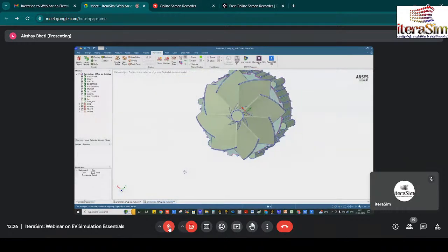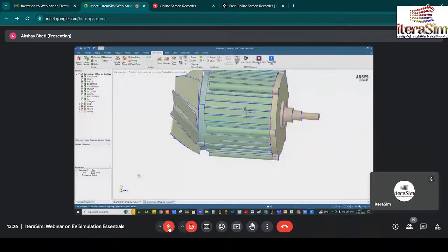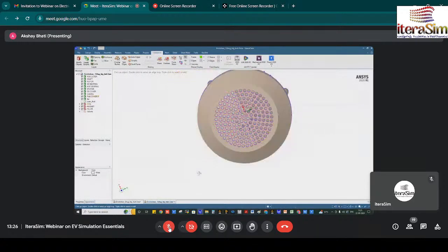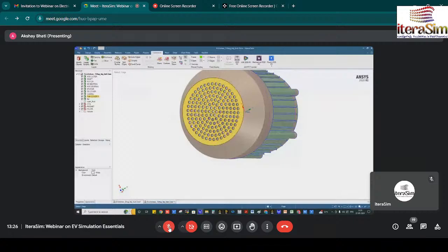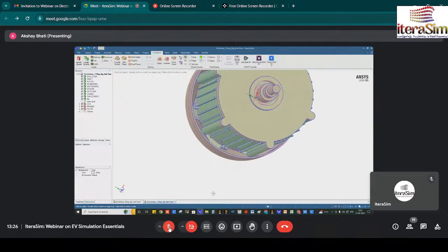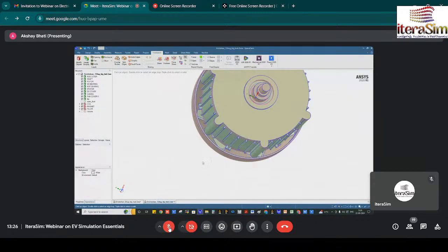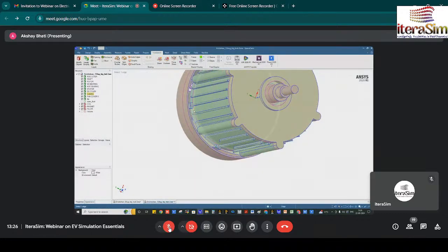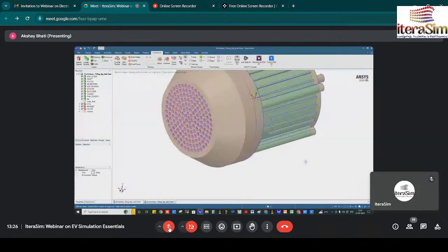You can check that fan over there to flow the air. After that, the fan cover will come, then you will get an idea how it is sucking or how it is giving. You see, there is a hole, air will go through this hole, and you can see the gap between the casing and the fan cover. You will find that the fan will deliver the air to the casing part so that it can cool the casing.